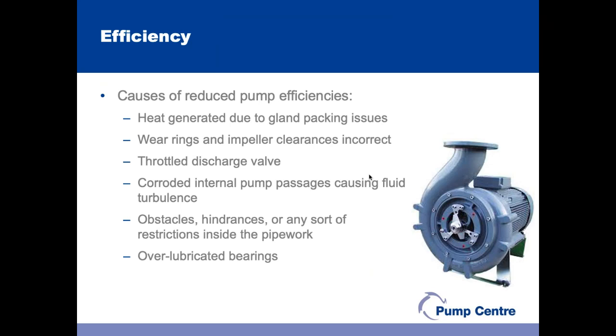Corrosion and possibly erosion of the internals of pumps can cause the fluid to be more turbulent than is preferable. That can result in additional losses and reduced efficiencies. And at a larger scale, any restrictions inside the downstream pipework, particularly on dirty water applications, of course.